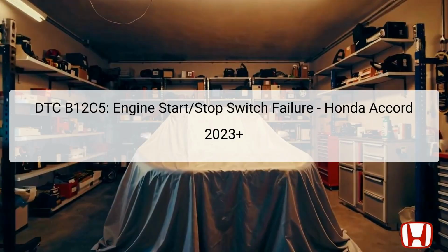The diagnostic trouble code DTC B12C5 corresponds to an engine start-stop switch failure in the 2023 Honda Accord. This issue arises when the body control module cannot recognize or detect the signals from the engine start-stop switch. The body control module is a crucial component that manages various electrical systems in the vehicle, including engine starting and stopping functions. Its location is typically near the driver's side dashboard area, facilitating connections with various switches and sensors. An abnormality detected by this module results in the storage of this DTC code.